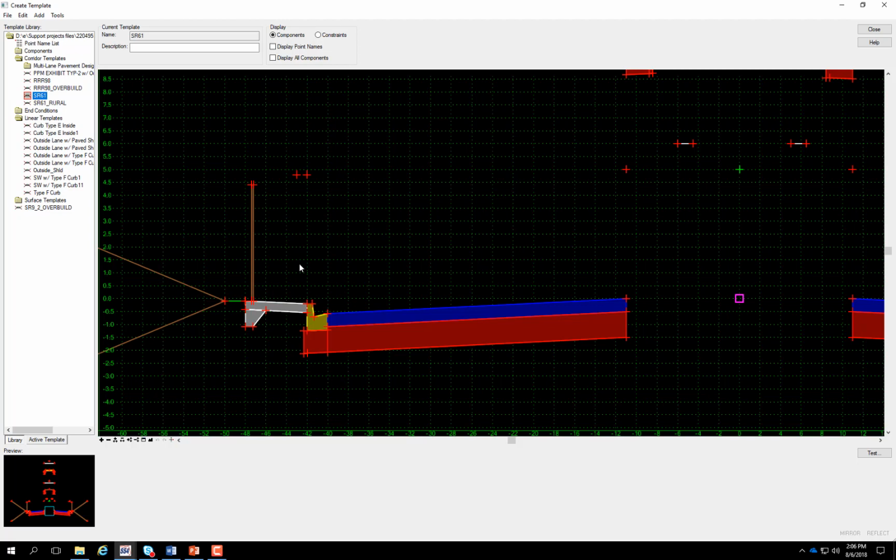However, with the change to the CAD manual, we've kind of sunsetted what was the old multi-line product, which would use cross sections and average end areas for our CEIs to compute volumes. In lieu of that, we're using more traditional approaches with surface-to-surface volumes, or surface-to-surface cross sections. So in order to do that, we need to deliver a subgrade surface.